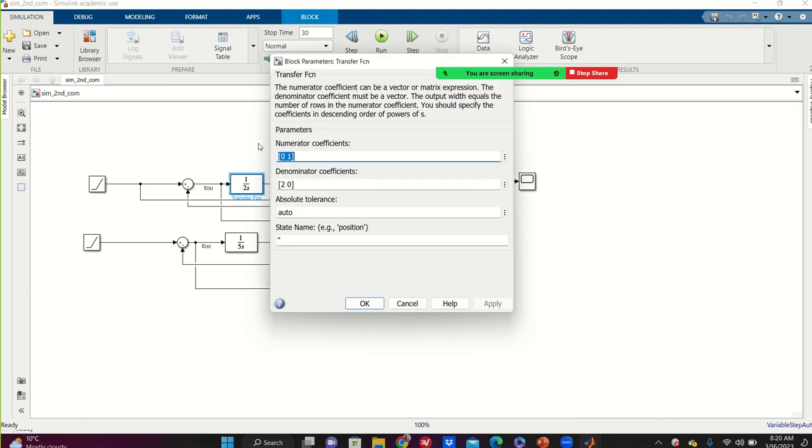I'm going to tell you why. Okay, so for the second order system omega n is 5, so it's going to be 25, and natural frequency, and for the underdamped system I'm going to say zeta is 0.2. Omega n is 5, 2 zeta omega n, and 0, because you have to put here what? The open loop transfer function.